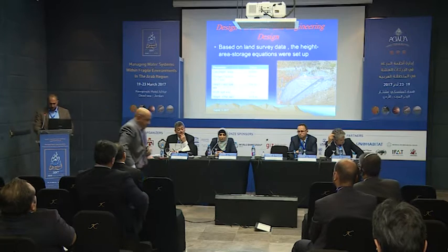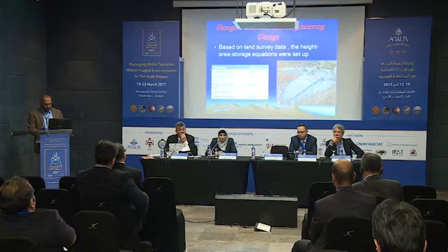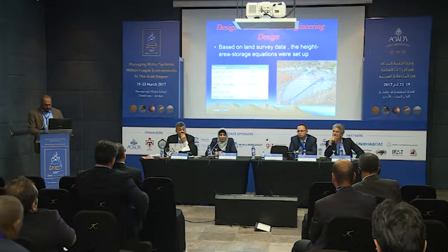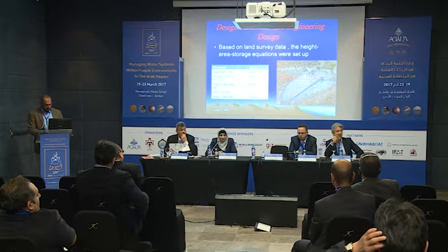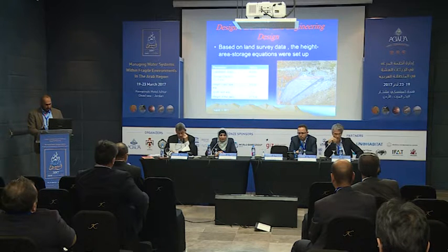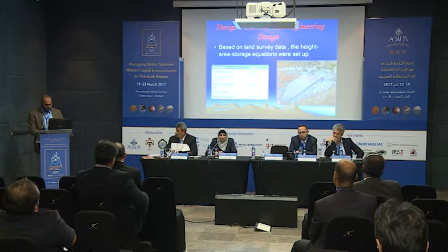The dam was already implemented in 2013, and the picture shows exactly this dam. Based on the storage capacity, we came up with the values: the crest spillway height is about 2.6 meters, and the spillway width is about 5 meters.